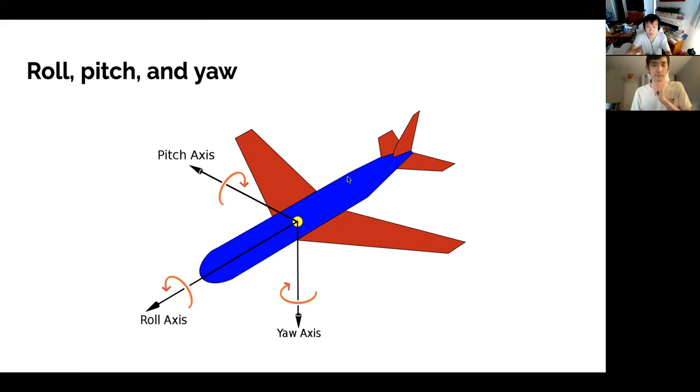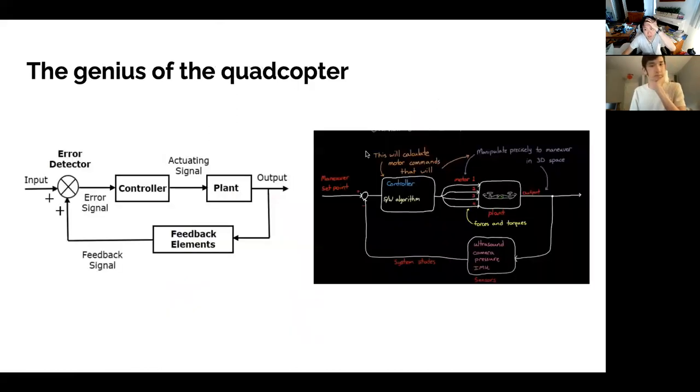Whereas roll is like tilting left, right. That makes more sense. Yeah, and then this is also really important because like you've done in your past lab, the complementary filter output is outputting a vector that's relative to its own reference frame. So we want to be able to qualify the X, Y, and Z into a roll, pitch, and yaw, and use this for our control system.